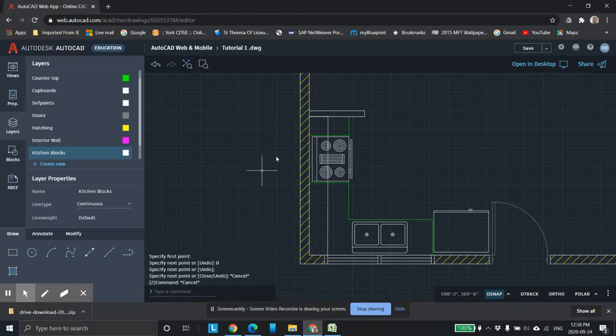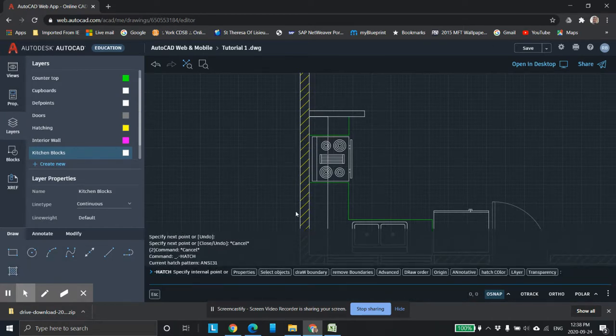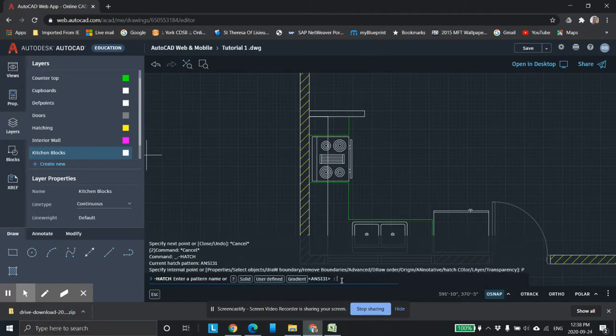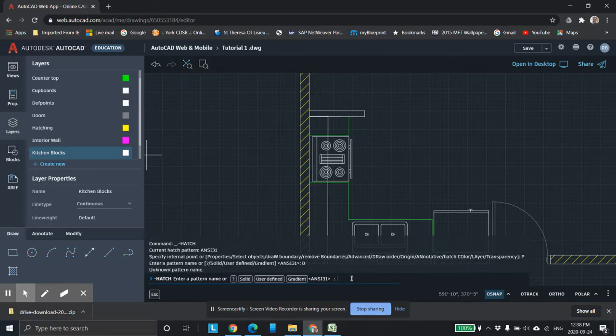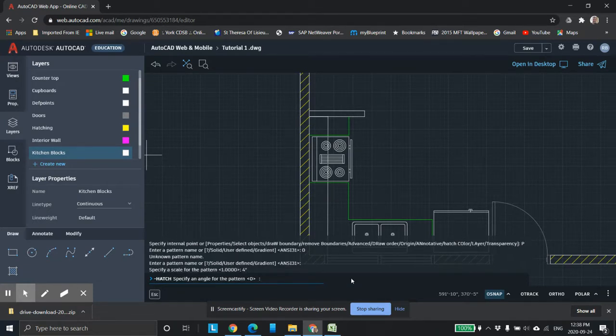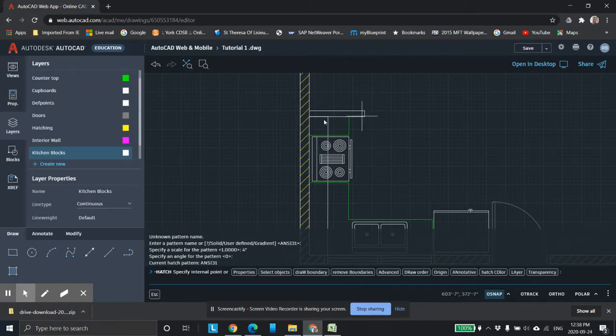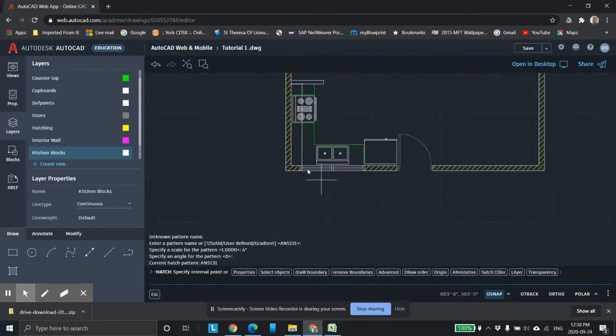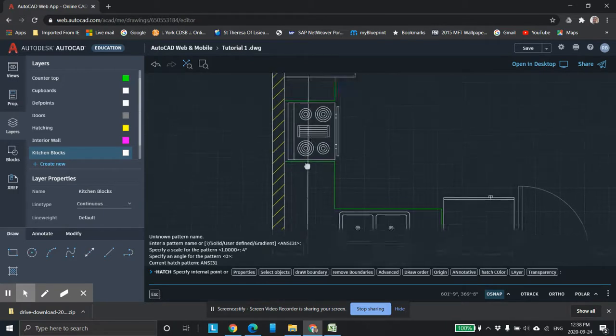Now, the one last thing I would finish up here is I'd probably cross-hatch that. I'd probably hatch that out just so you can see that it's a cupboard. I mean, yeah, we've got it written as cupboards here, but I would likely do that. And properties. I'm going to say, let's leave it at 90 degrees, or 0 rather. And distance, I would say 4 inches. 0. And I'm just going to see if I can fill that. Okay. Kind of a bit too thick, but nevertheless.